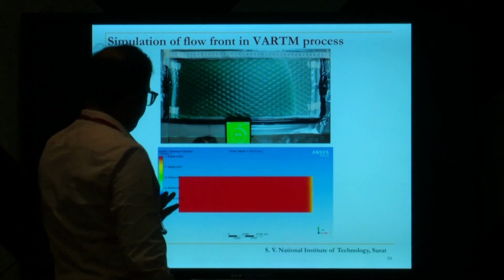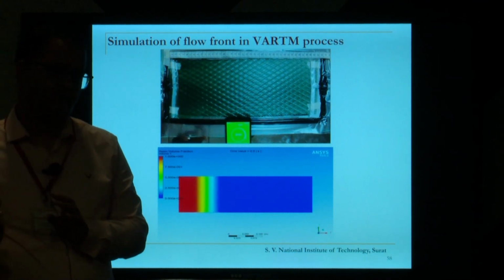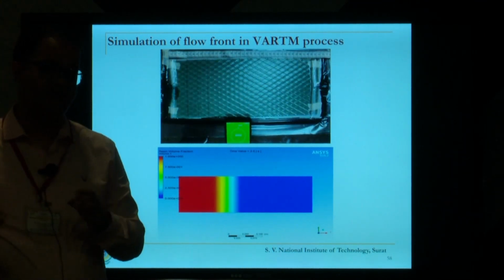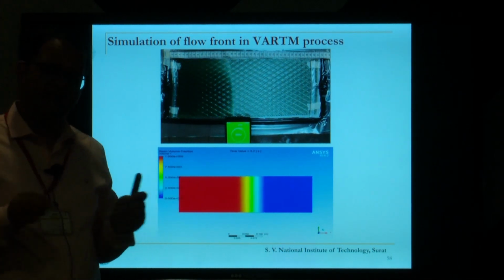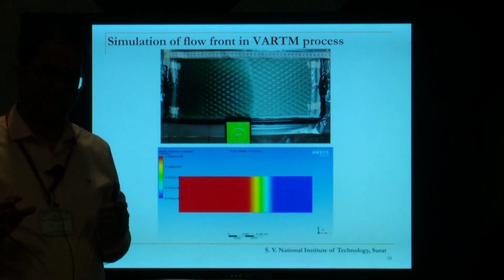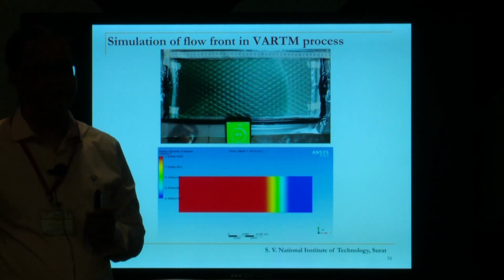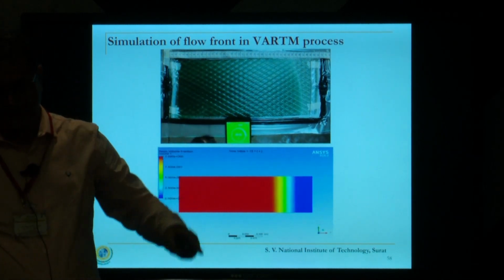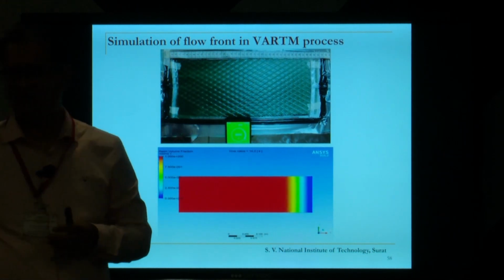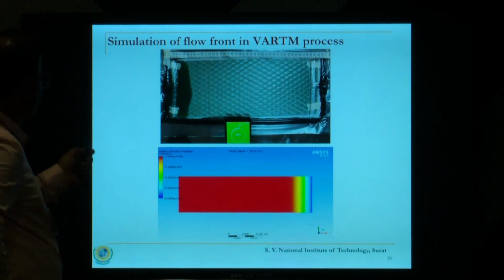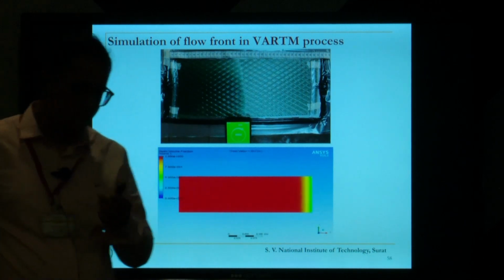Initially, we studied through simulation, and then we decided on 2-3 specific gate conditions. With that gating system, we could reduce the number of experiments we had to perform. To make a part takes 1 to 1.5 hours, but the waiting period is 24 hours to get the part out. Until then you cannot repeat it, because the mirror glass is the only one you have. If you have multiple, you can keep fabricating multiple parts, but that is how the study process also becomes slow.